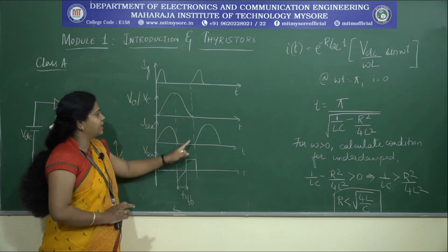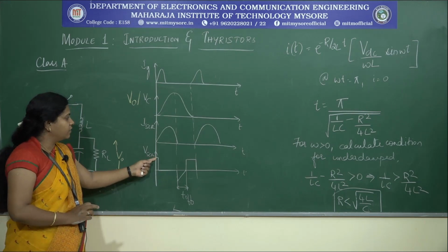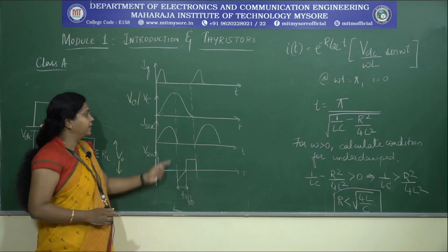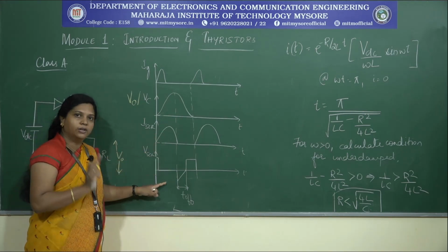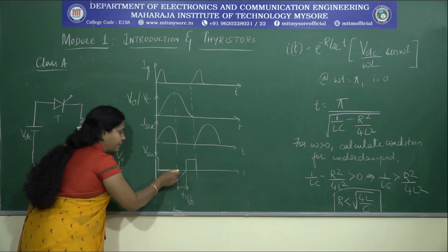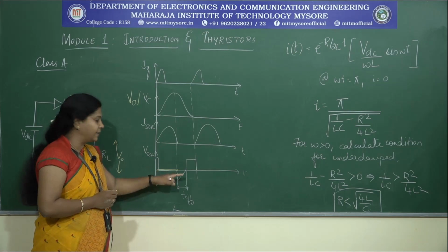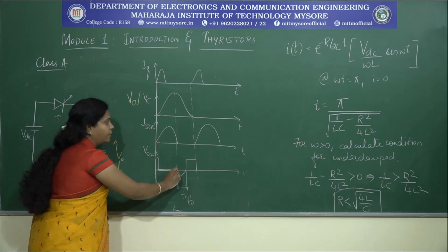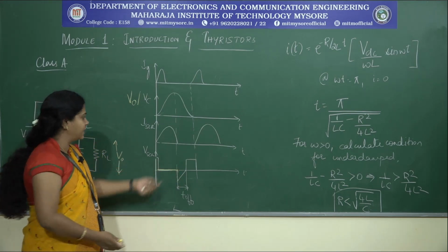And when it is off, with respect to the voltage, there will be a voltage across the SCR. When the thyristor is in its on state, the voltage drop is 0.7, so we represent the on state as a straight line. This straight line will not stop here, because of the minority charge carriers, as we have previously explained.